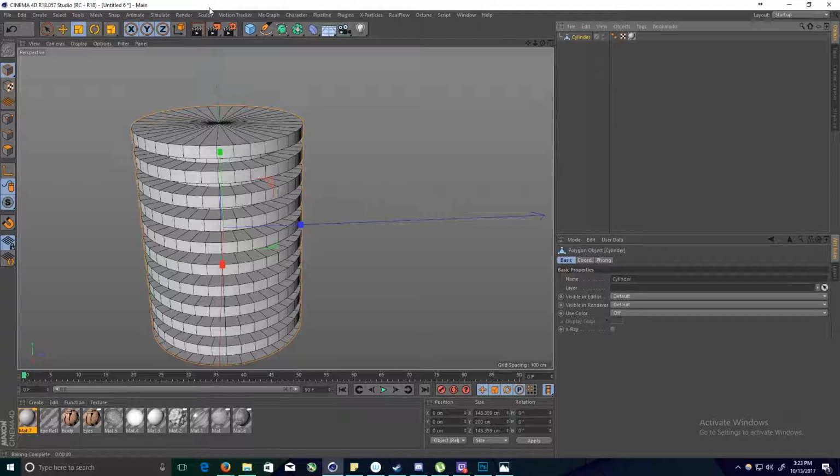the function is the same. You have a high poly model, low poly model. You just tell your renderer or whatever your program how it handles baking. Just tell it to use this high poly reference and calculate a displacement map based on this low poly frame. You can also do the same thing with normal maps if you wanted to. You have to calculate that out.